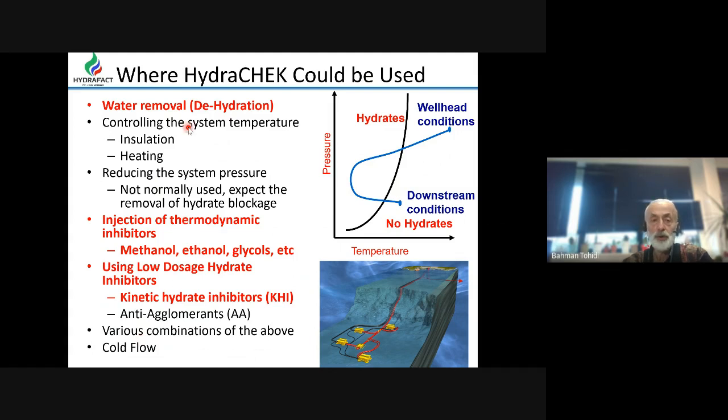Now, the oldest one probably is dehydration. And then I mentioned other points: controlling temperature, controlling pressure, and then injection of thermodynamic inhibitor, methanol, ethanol, glycol, using low dose hydrate inhibitor, kinetic hydrate inhibitor, anti-agglomerant, various combinations, and cold flow.